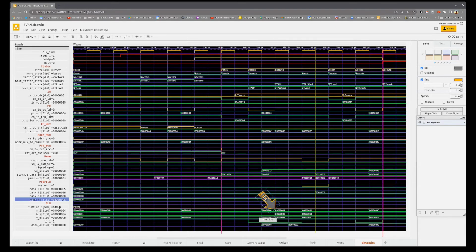is a combinational circuit. So all the values, flags, and signals that were set up, immediately the ALU begins responding to those. We can see here that the register file has fed into the ALU the 28. That's the X4 value from here, from this bank. We can also see that the immediate value from the instruction itself is now present on the input to the ALU. And again, because it's a combinational circuit, the answer is available immediately, and sure enough, it is 32.